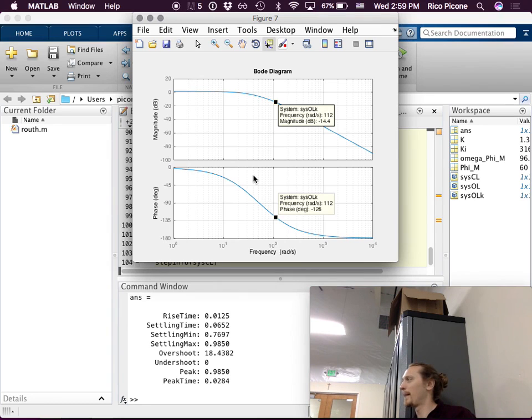Yeah. So when you're shaping it, the Bode plot doesn't tell you if you go unstable. So how do you be cautious about that? You can always go back to the Nyquist plot. That's actually not part of the procedure that Nise recommends.